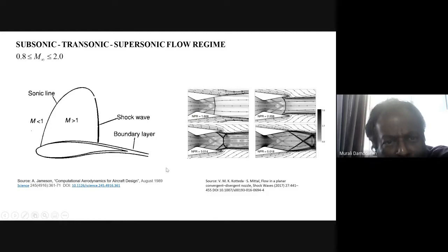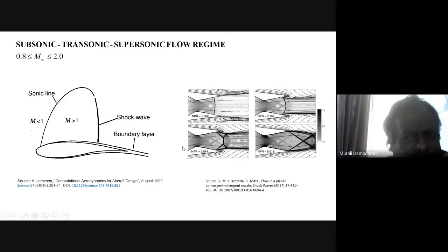Flows are also computed inside high-speed nozzles. For nozzle designs, we want to see the presence of shocks like this. You can see complex structures and expansion waves. This is all solving the full Navier-Stokes equations by finite volume methods.